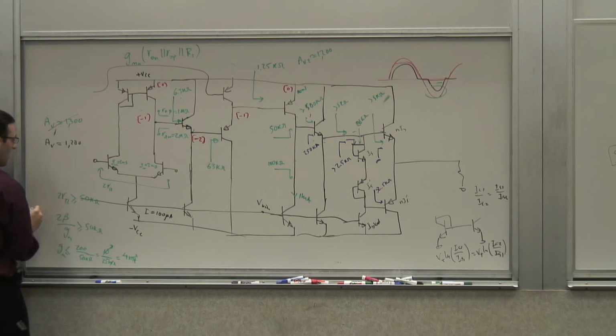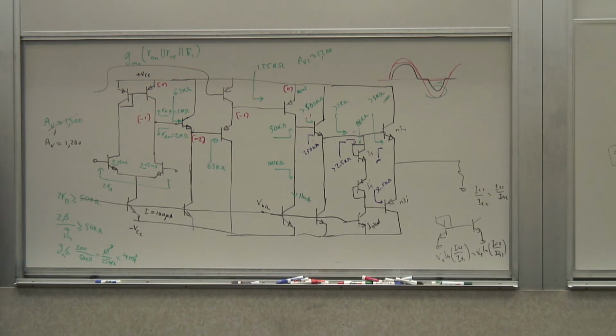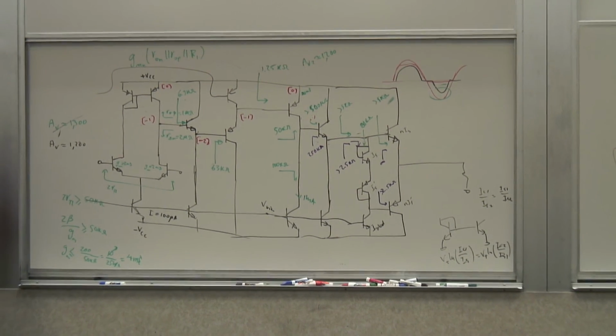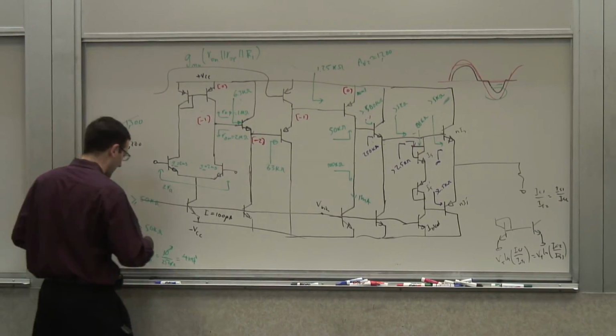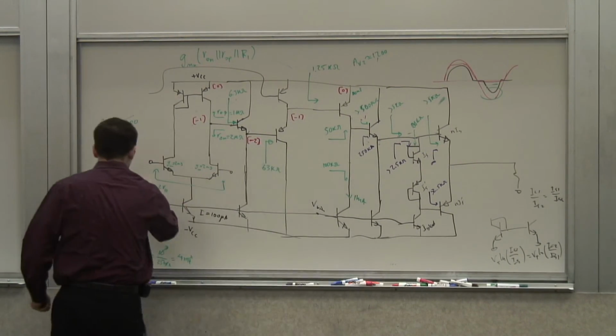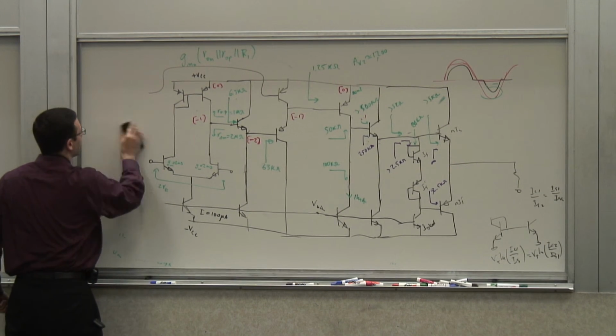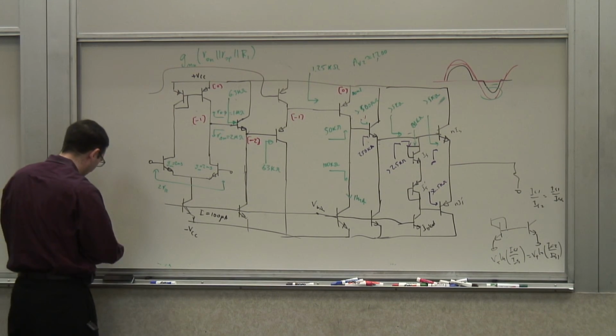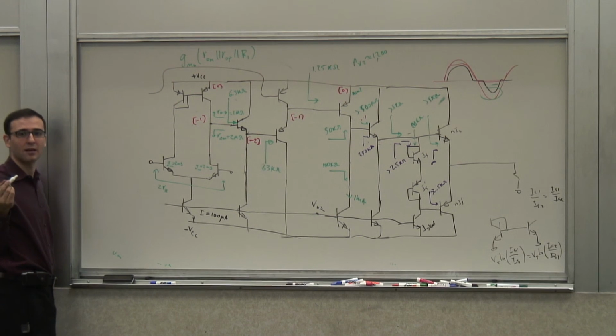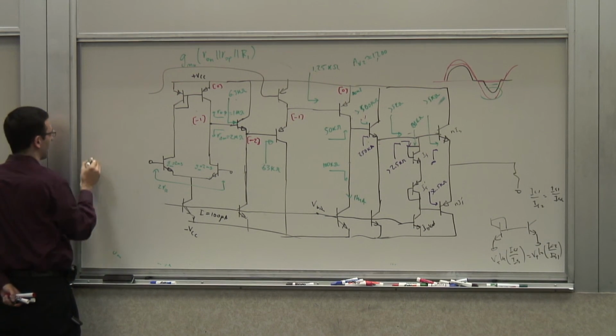And now, I want to bias this in such a way that my gain properties, for instance, don't change too much, right? So I need a constant GM core. Let's say I want to bias it with a PTAT. So I want to keep my GM constant, which means that I have to make a current source that's proportional to the temperature. So I know how to make that core, right? So let me just erase this stuff. So I need to make a PTAT core, but basically I need to make a VT, kT over q core. I know how to make that, right?